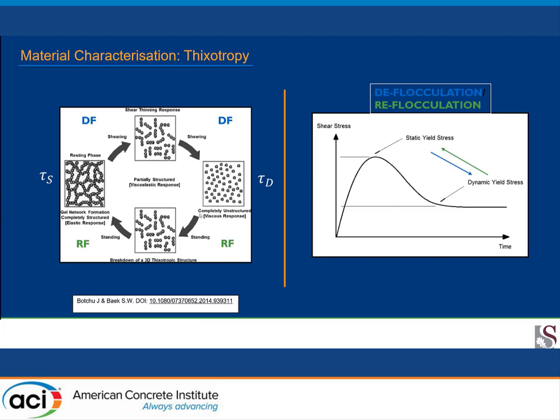And then if you leave this material standing, so this is obviously after you extruded the material, then it will start to reflocculate to regain this partially structured microstructure. And then if it stands further, you'll get this completely structured microstructure, and then you get elastic response. So if you look at this graph on the right, this is essentially what you get.